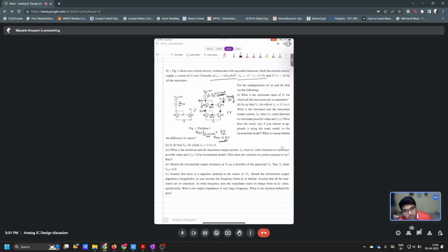The most susceptible, the first transistor that will go out of saturation will be M4. Okay, always remember that. I mean, for properly biased cascodes. That is the general thing. This cascode transistor will be the first one to go out of saturation. Only and only after that M2 goes out of saturation. That is in general how it is biased also.